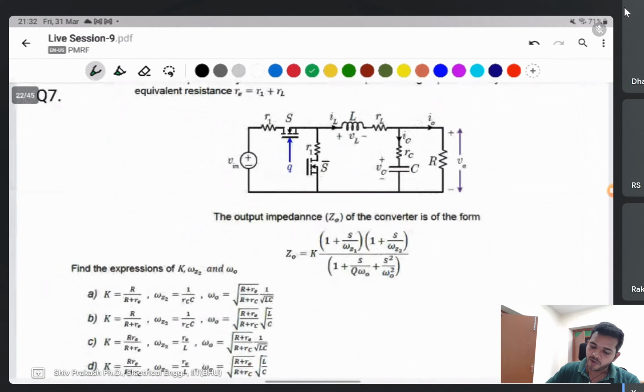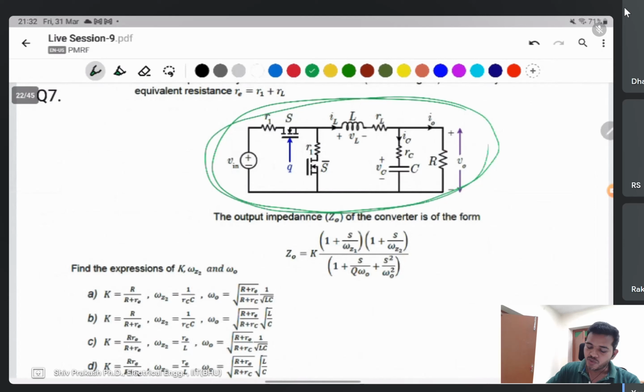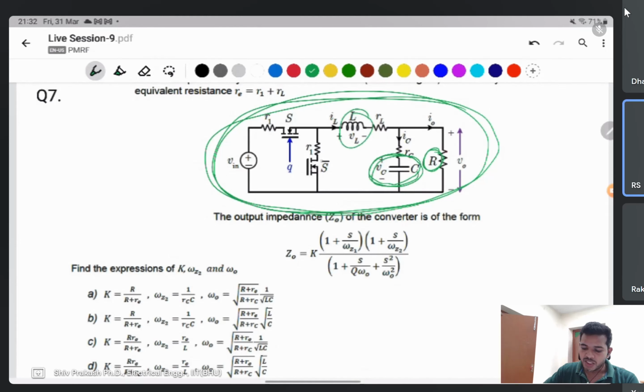Because in a power electronic system, in any converter, you can change only the duty ratio of the switches. You can't change anything else in the converter, because the load resistance is not in your hand. Once you design the converter, the capacitor value and inductor value are fixed. The switches are fixed, you can't change them in running condition. Input voltage is not in your hand. Once you apply the input source, leave it. We have only to control the duty ratio of the switches.